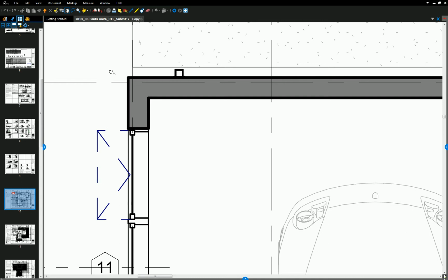So in our stud wall, of course, I picked the crappy marker. Your foundation would go down here, something like that, right? The grid is aligned to the exterior face of the stud. And then the finishes, the plywood sheathing goes on the outside, and then your siding or whatever it is, okay, or plaster or something like that.